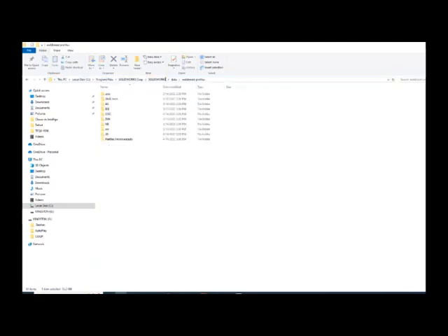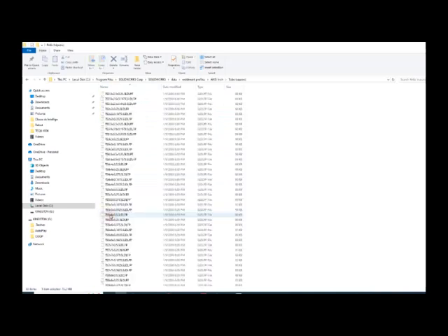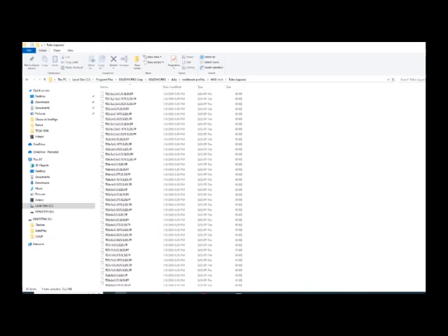and cancel, get out of here, and now you go to your C drive or anywhere you want. Delete what is there and put in the directory that I copied, where my Weldment profile is. Hit enter, and you are right here. Here is ANSI inch, the library of ANSI inch. Here is the tube square, but it's not what you're looking for. There's no 1 by 1 there at all.